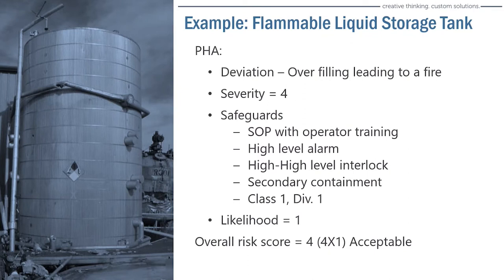That's typically how PHAs work, especially ones where people are very familiar with the process and you've been doing this for 20 years, and this is kind of how it works. Well, what LOPA does is LOPA takes a look at these safeguards, and rather than just qualitatively saying yay or nay, or yeah, I'm comfortable with that or not, it actually puts a number to it as to what likelihood there is of failure of these safeguards.